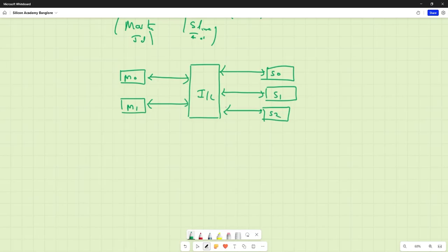By interaction, we mean that we are going to write and read within these slave devices. A slave will have its own memory, which I'm representing just as a block with addresses 0 to n. Each address could represent a byte, or a 2-byte location. So this is the slave memory.